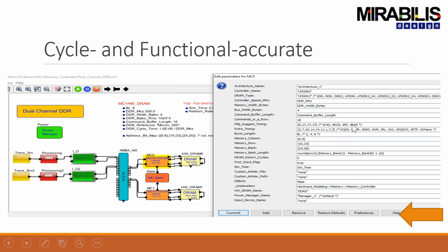timing parameters, looking at RP, RCD, RAS, looking at things like, for example, the WTRs, the RTPs, the WLs, the RLs, such that I can also start incorporating addresses into my system and feeding it in here, so I know exactly, okay, I've been to bank 1, row 3, column 1, and then I'm going to go to bank 8, row 4, column 1, and it actually has CCDS, because they go across bank groups.